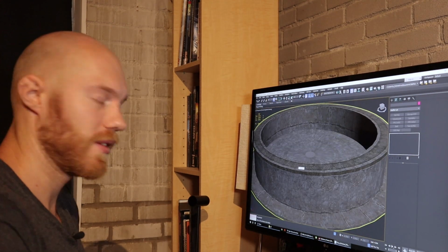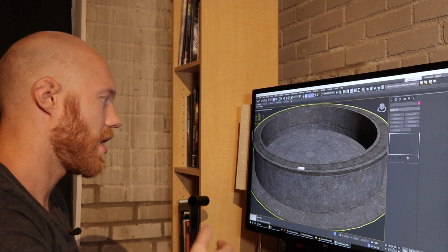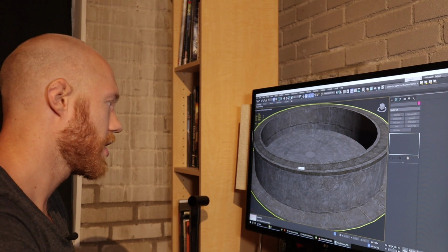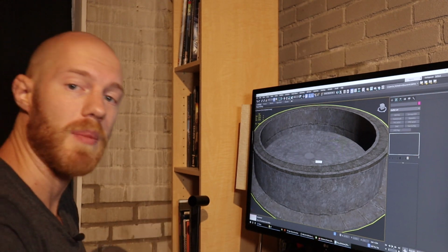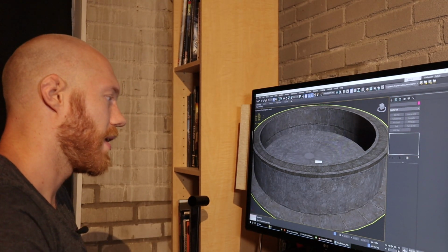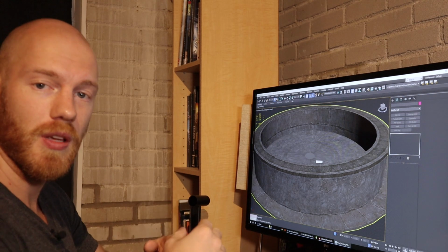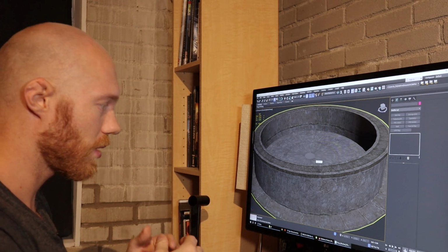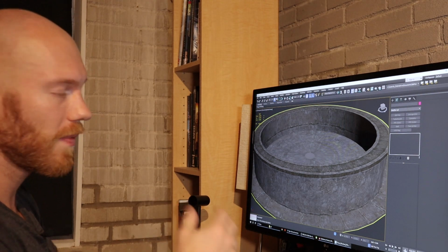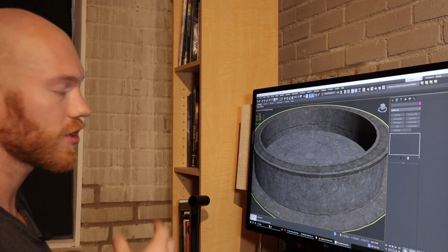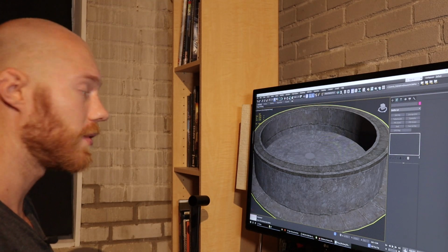So I'm going to go through and literally use those same 2 techniques to UV the rest of this mesh. And then we're going to catch up at the end, and I'm going to show you how to deal with your lightmap UVs in terms of having all of these strips on top of each other. When we bring it to Unreal, we're going to want to render out some light maps when we bake our lighting, and if they're all on top of each other, it's going to give us errors and problems, and I'll show you how to fix that with the second UV channel.